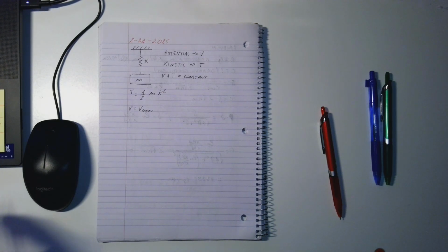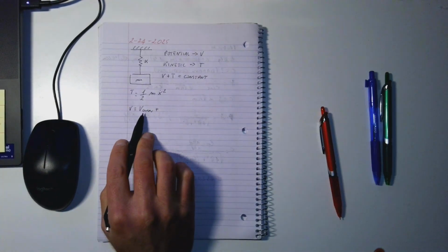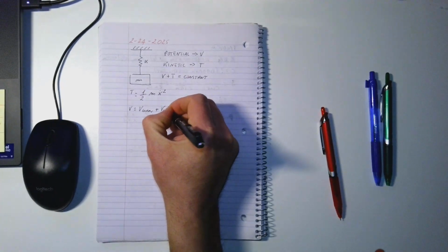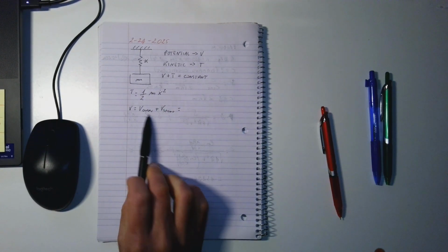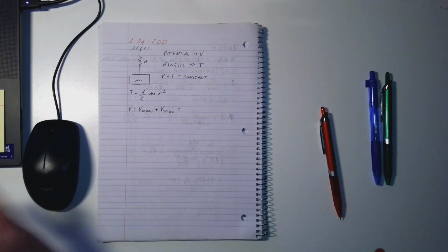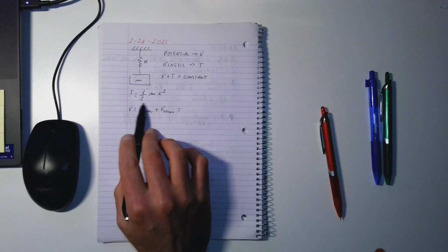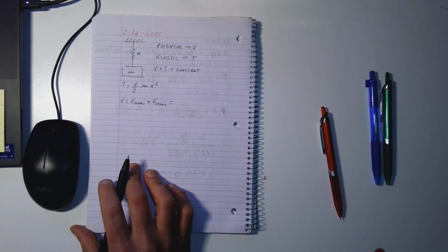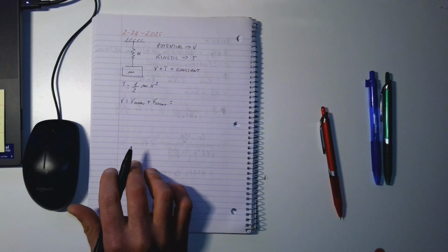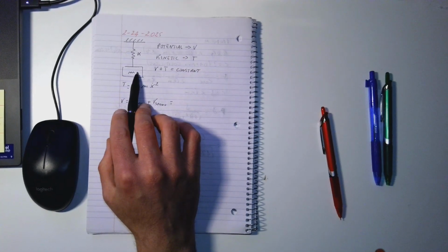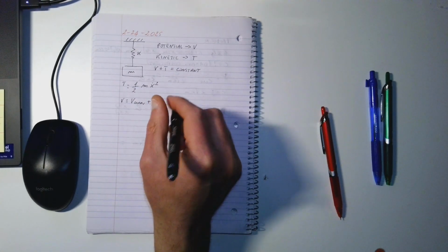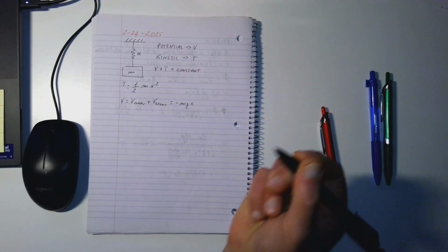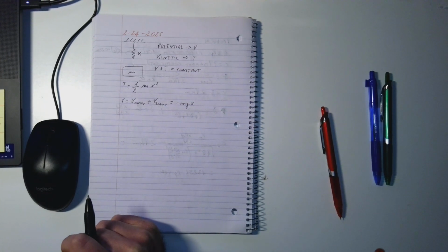So we have two forms of potential energy. One that comes from the force of gravity, and the other one that comes from the spring. We have to include all the forms of potential energy. The gravitational energy depends on the mass of the body, and we write it as negative mgx. Again, it is related to the location of the body.